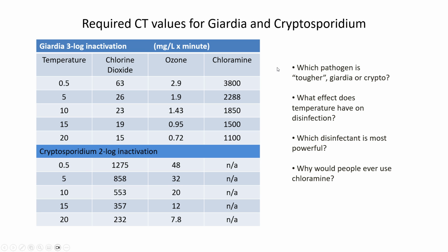So people like chloramine in the sense that it provides good residual protection. Sometimes they'll take a balanced approach where they would have both chlorine and chloramine. The chlorine gives you the fast, powerful disinfection. The chloramine provides residual protection.